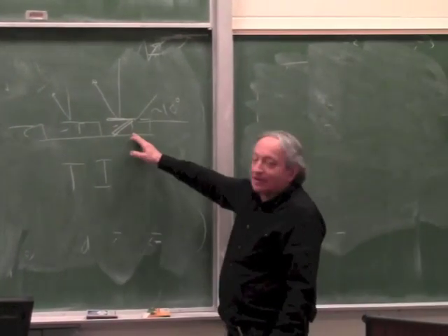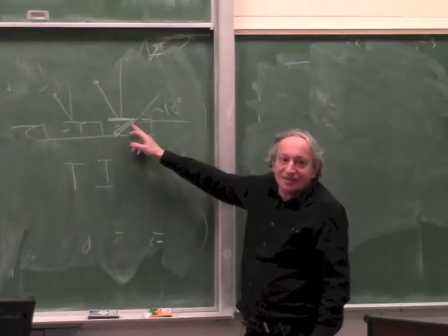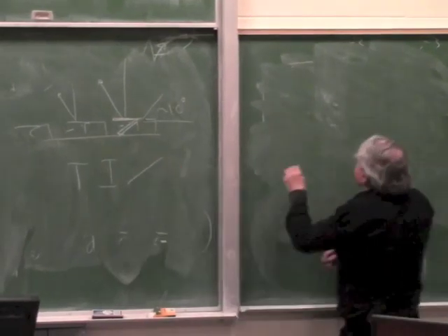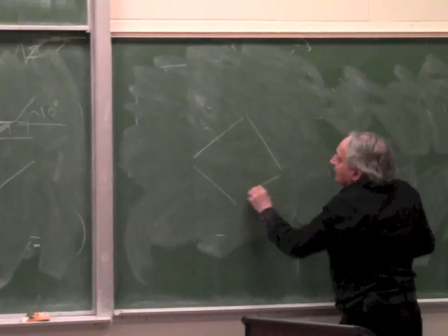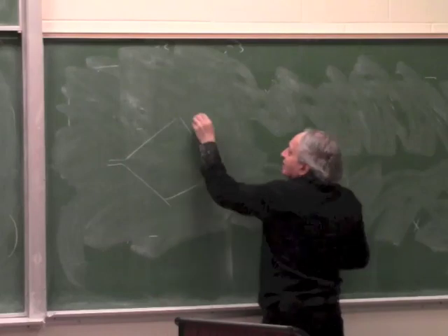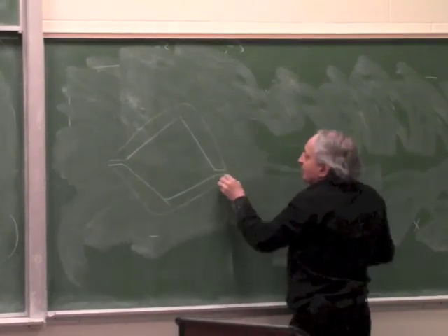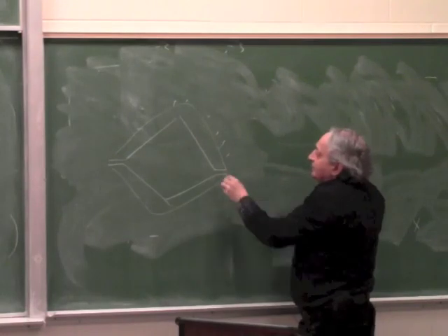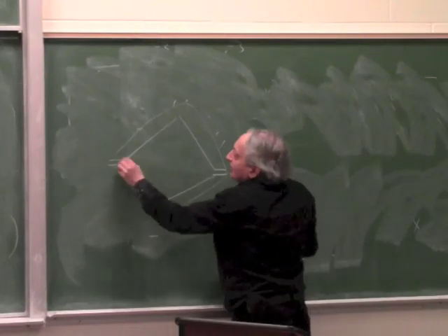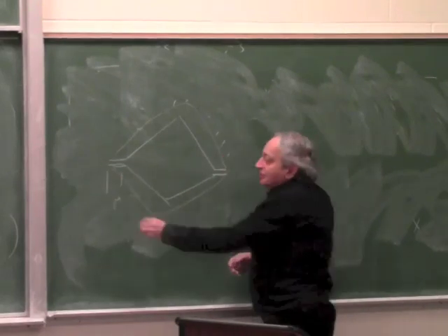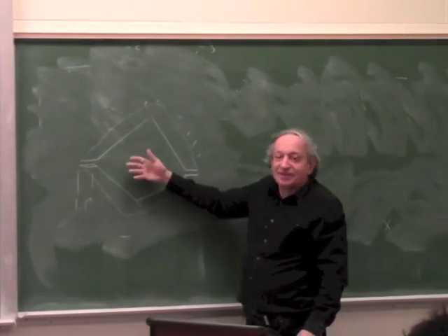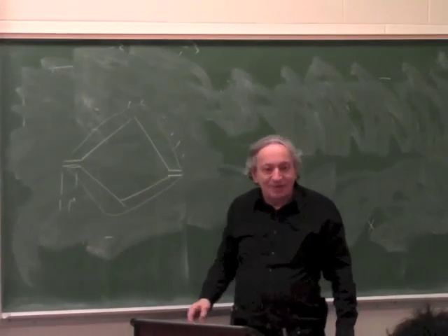And if you really want to see how they make them, they look like this. They are not a cantilever, because this will fatigue too fast. Each mirror looks like this. And then here they have a strip, and it's a torsion hinge. So this is the opening. This is steady, and this mirror tilts like this. The torsion hinges are about 1 micron long by half a micron wide, but they only twist 10 degrees and they last forever, which is quite surprising.